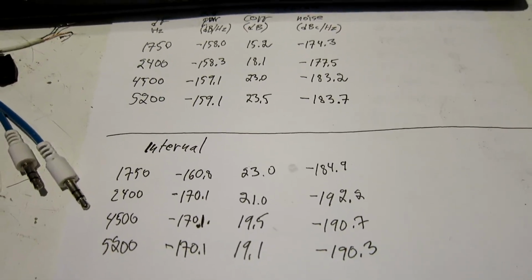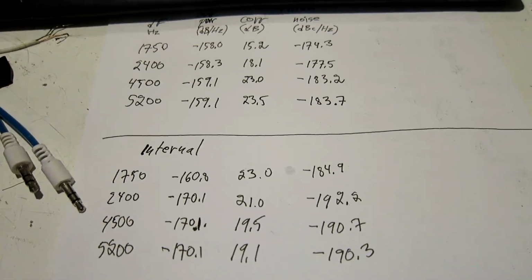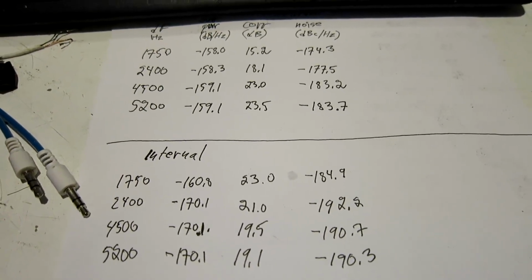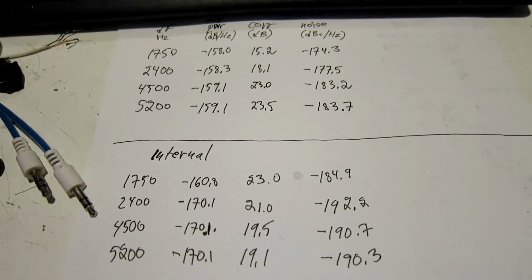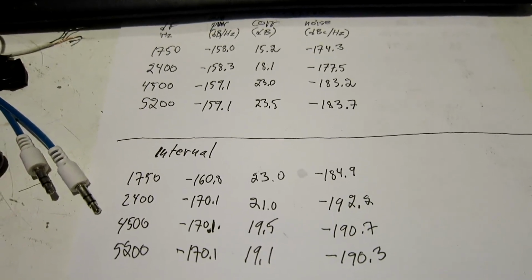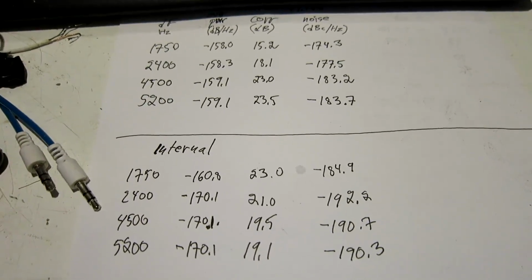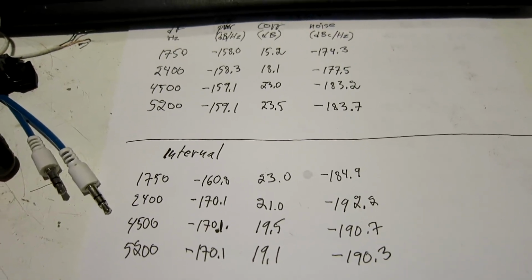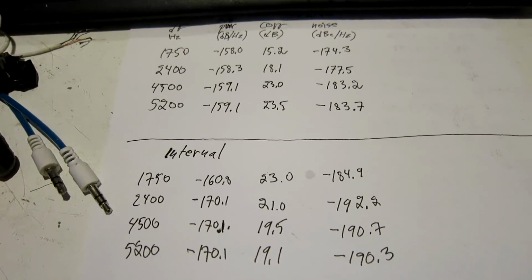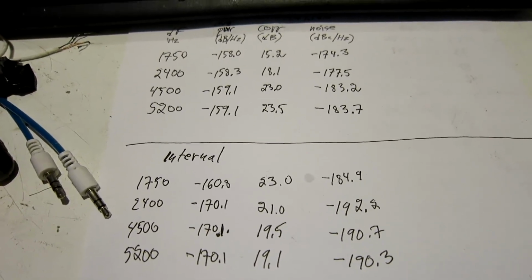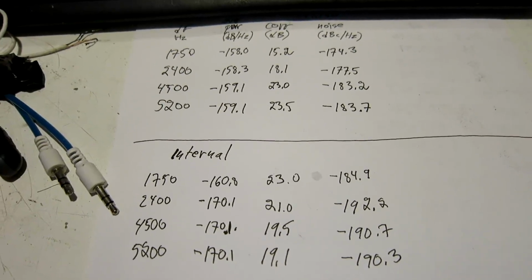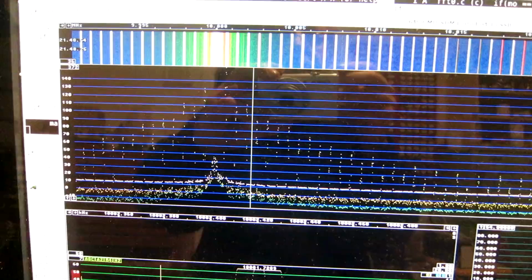For close range, I can use a lower sampling rate, and that will ease the rounding errors from the transform. And as you have seen already, at wider separations than about 5 kilohertz, there is some other problem. I don't know if it will survive or not at lower sampling rates, but I will try that now.